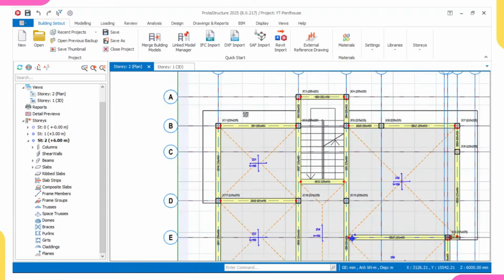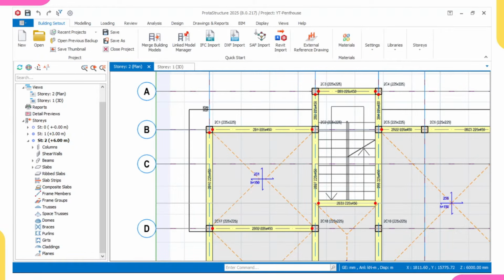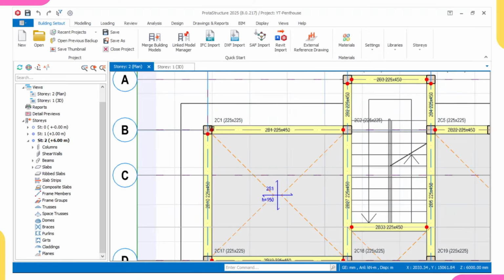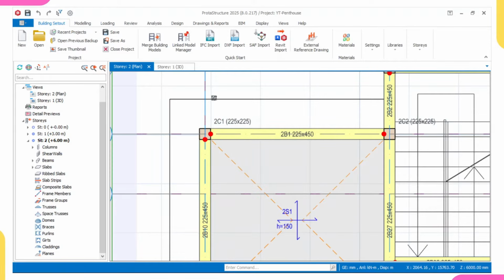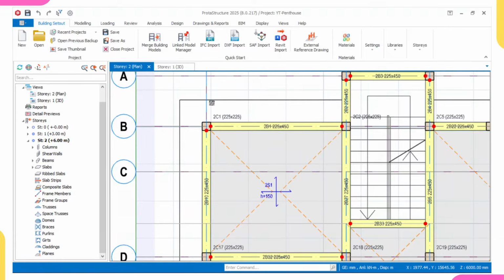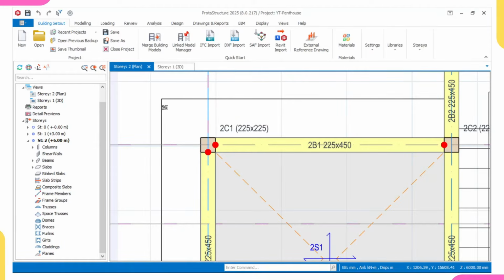So before we can model those cantilevers, those slabs, we can just model the slab on its own, because they are cantilever slabs. They can easily be modeled. We don't need to insert a new grid line. But don't forget we will be inserting beams and columns, like we are having a column at this point.